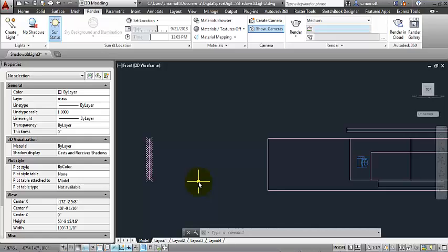So as I said, if you add up the 2 risers plus 1 tread, you should get a value between 24 and 25. So let's start with, again, calculator, take in 24, and then minus the 13.7, which was 2 risers. So that would say that my tread would be 10.3. And if I was to take 25 minus 13.7, I would get a value of 11.3. So basically my tread wants to be somewhere between 10.3 and 11.3 inches. We can round that to 11 and we'll have something that's a little bit easier to work with.